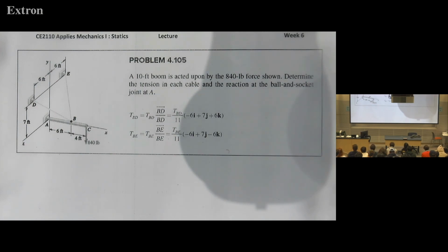And then one side is free. The other side is ball and socket joint, and then that is 3D pin. Okay, 3D pin has no moment but 3 force reactions, right? So that's what we can remember, right? So this is a pin, and then this is 3D pin, so there are 3 forces to include in the free body diagram. So that's what we need to think about.